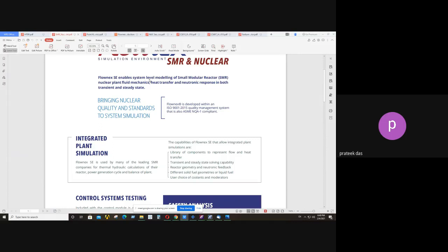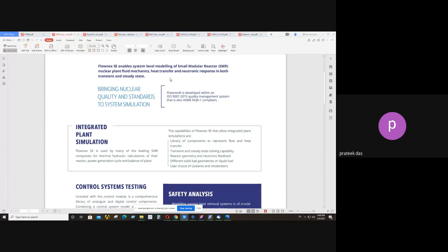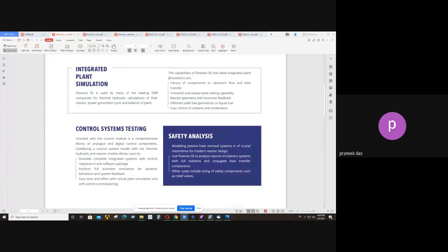Utilizing this software and applying those API configurations, those Fortran DLL libraries were linked to the Flownex environment. So it can perform co-simulation with Fortran code, in which all the neutronics calculation is done, and all the flow-related and heat-transfer-related calculation is done in Flownex.